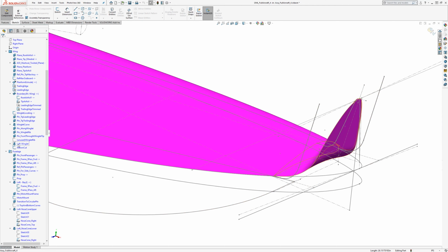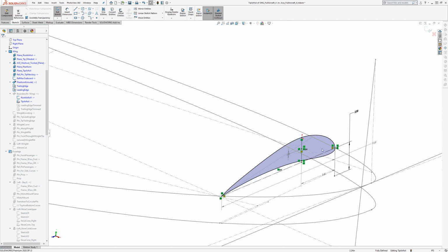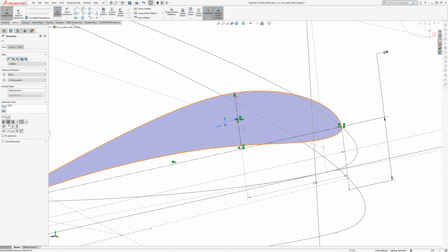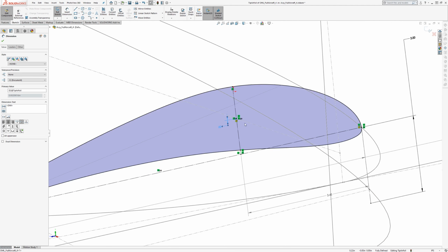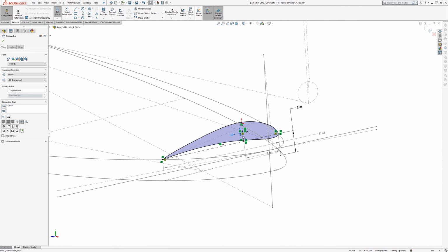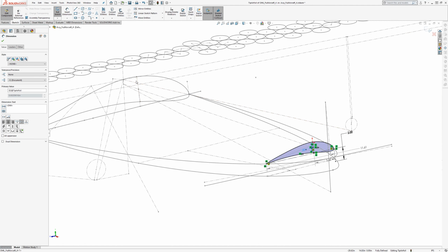So if we go back to the tip airfoil sketch, in there I have a driven dimension measurement of the midpoint of the deepest section of the airfoil here at, I think it was the 30% chord. And that is measured against a point that's piercing the dihedral layout, just to make sure that the root airfoil had that midpoint forced onto this line.